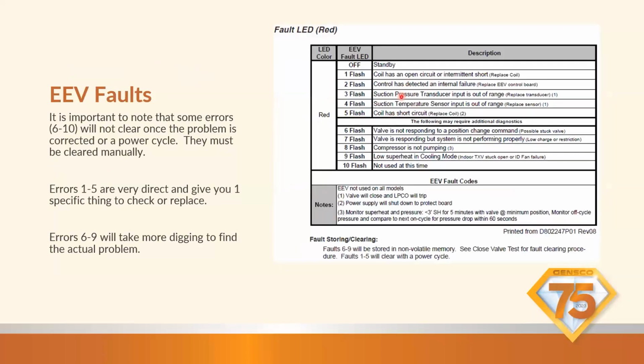Okay. That's easy to test. We can unplug it, test it. I'll show you how to test that. Flash 2 on this board, it says it's got an internal failure. Really no testing to do there. If it's giving you a 2 flash, there's something wrong with that board.